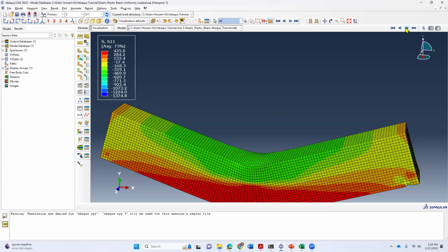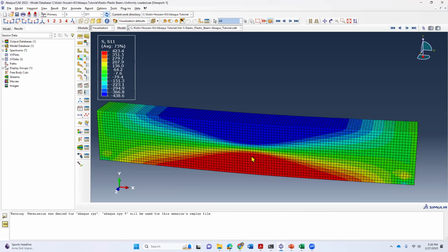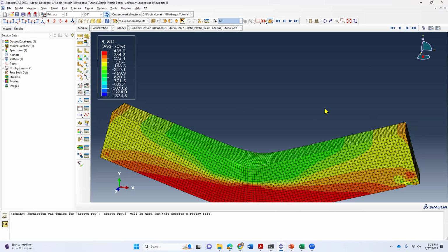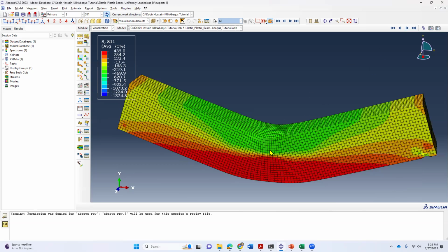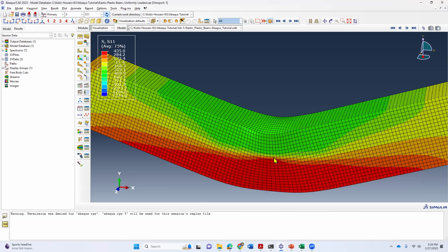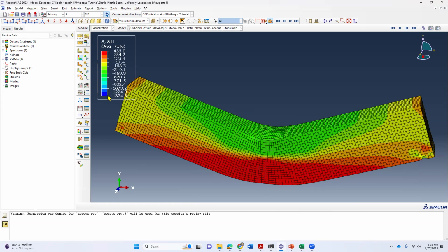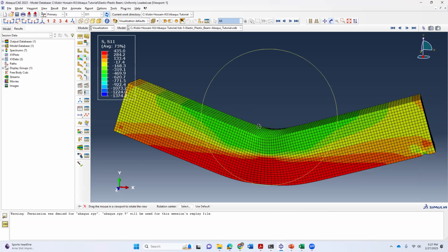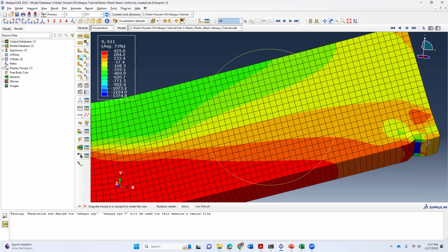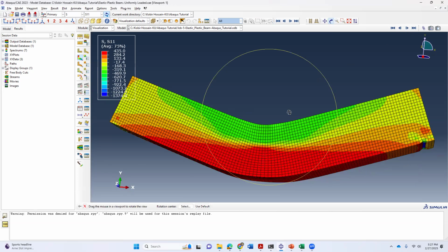Okay, and right before plastic hinge formation at the mid span, you can see probably the unyielded part of the beam is like 1 inch or so, and then in the very next step, the beam deflects a lot, and you can see all the elements above neutral axis at the mid-span especially has yielded, and also at the bottom it has yielded. We can see some extremely high compressive stress, but that's not here. It's at the support actually. You can see the blue region. So we see it there.